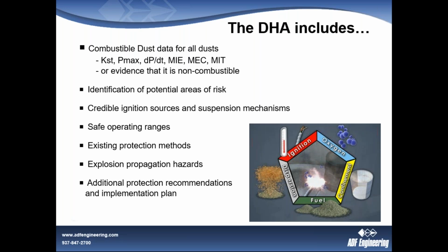So you'll have a small explosion in a dust collector, and if it's allowed to travel down the ductwork to a blower that has an inlet air filter, this inlet air filter will let that explosion travel outward into potentially a room that may have a layer of dust, and that entire room can go up into an explosion as a secondary explosion. And that's the primary thing that we're looking for. How do we prevent secondary explosions?